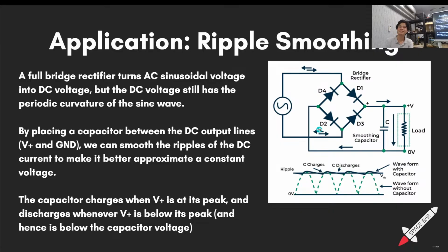Yes, they will recommend a specific capacitor to use. But if you are concerned with the peak to peak of the DC waveform, you look at the absolute maximums. That determines which choice of capacitor to use, and the bigger the better.